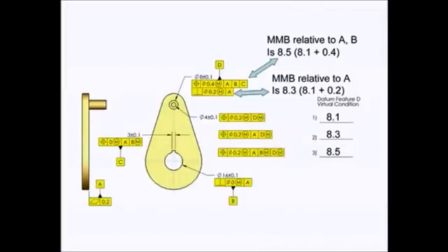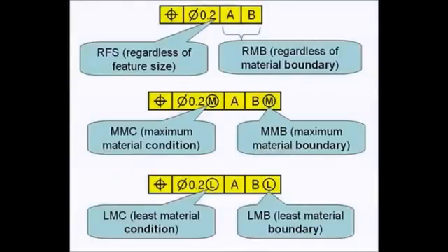Yes, and there's some new terms, and along with that we have maximum material boundary and least material boundary, so when we see the modifiers on the datum references, now they all have a common term. So there's a lot of things that have changed in the standard. We have new concepts, we have expansion of principles, we have brought it up to date with the other Y14 standards. And in about a day's time, you too can be updated to this 2009 revision of the Y14.5 standard.